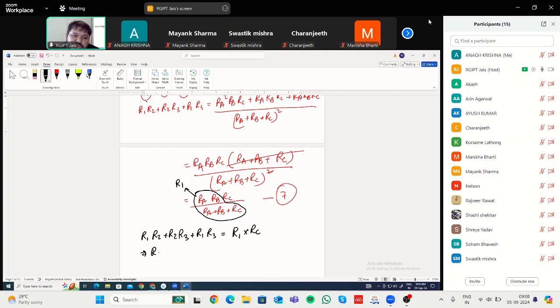So you can find RC to be R1 R2 plus R2 R3 plus R1 R3 divided by R1. So you have found RC in terms of R1, R2, R3.